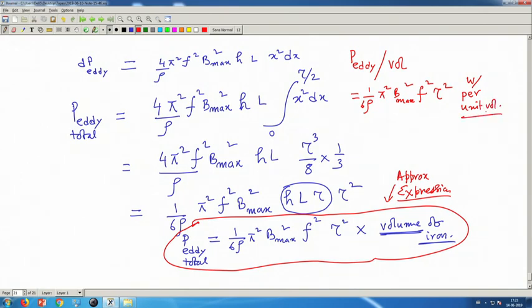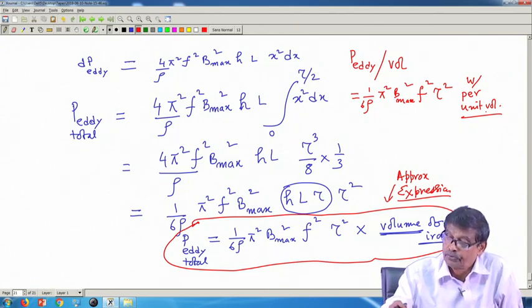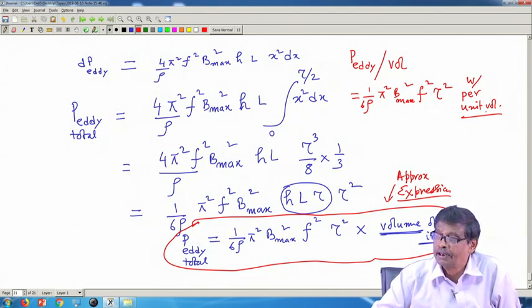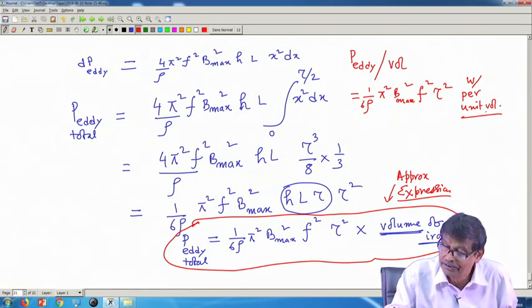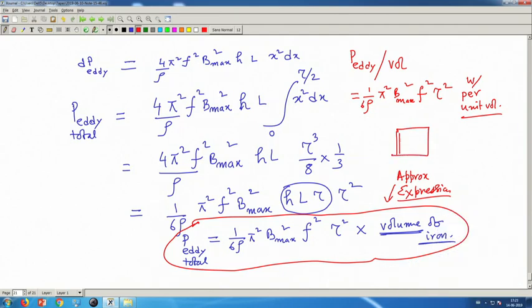And we say that then eddy current loss will be proportional to the square of the thickness of the plate. All these things, the argument was, if you use a solid block of iron, eddy current loss is bound to be more, so many eddy paths.